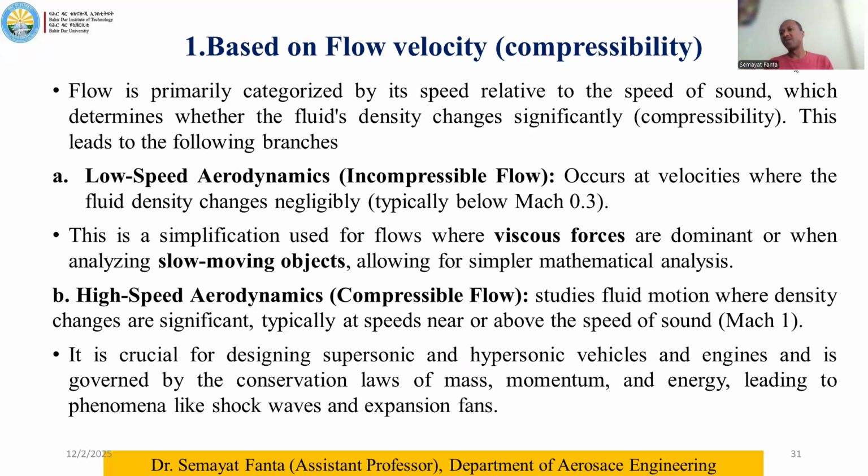As we go up each kilometer, we find about a 6 degree Kelvin, or 6 degrees centigrade, decrease in temperature within the first 11 kilometers of altitude. So that effect comes into the picture through the speed of sound. You can calculate the speed of sound for every altitude using that square root of gamma R T formula. So Mach number is M equals speed of object divided by speed of sound.